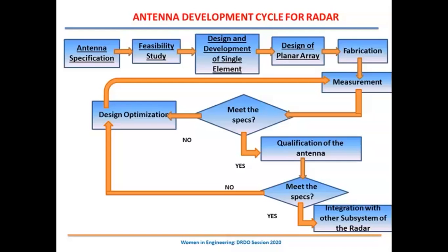So when you design it, that is also one of the important parameters of the antenna specification. The components, for example the connectors that you choose, should be mil grade if it is for a military application, or qualified for airborne use. The vibration levels and environmental qualifications are very different, because you have to emulate the environment in which the subsystem is going to operate. It has to withstand those harsh environmental conditions. That is one of the important aspects while we consider the design of the antenna.